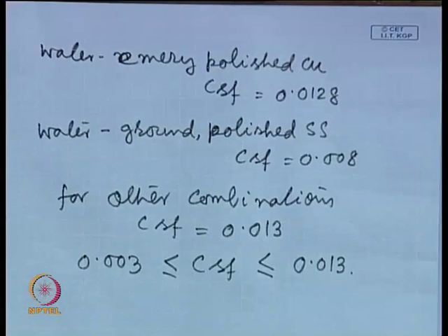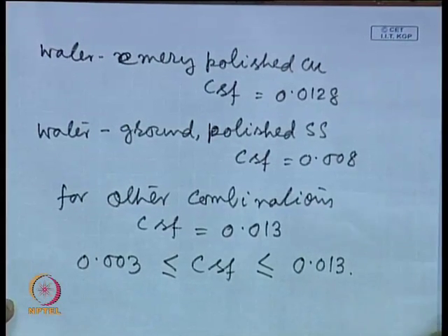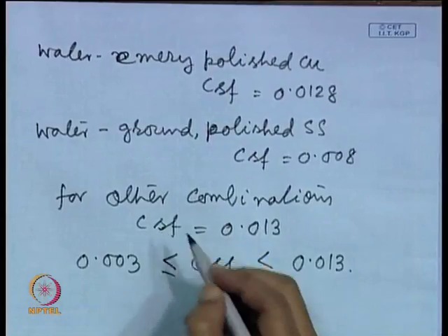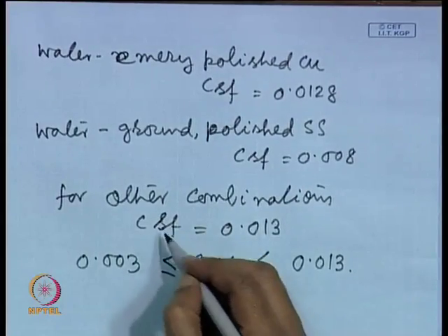Okay. Now, what is the reason for the success? We may feel a bit awkward because we are familiar with much higher accuracy of prediction in other cases, but in case of boiling heat transfer this is a good success, and people say that the root of the success lies in C_SF. This C_SF takes care of many stochastic variables in the process of boiling.